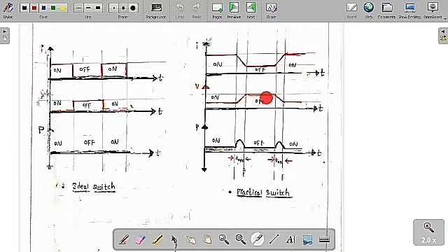You can see clearly that this is called the switching off condition. When you are switching off, the current is going to decay and the voltage is going to increase. Therefore, at the off position both are non-zero, so the product is also not equal to 0. That is the steady state, but during the switching conditions also, if you take the product of these two, you are going to get it in this manner. Again it is going to repeat. This is the switching on condition and this is the switching off condition, called T on and T off.